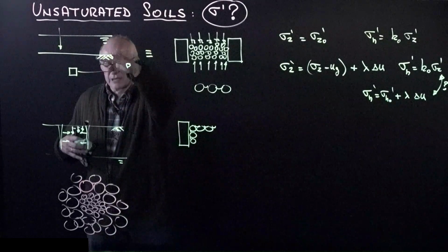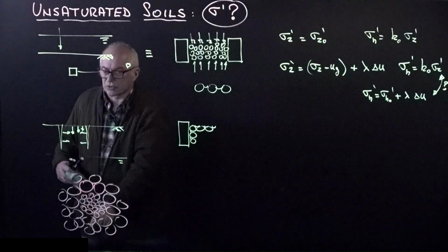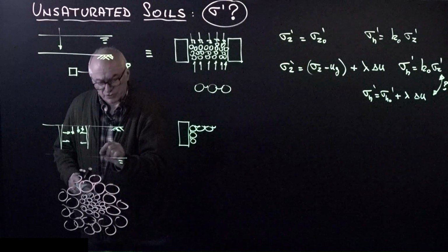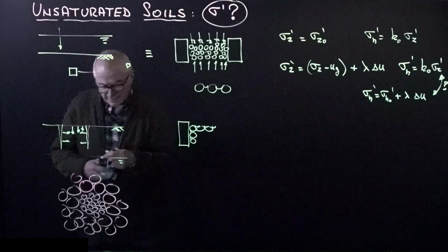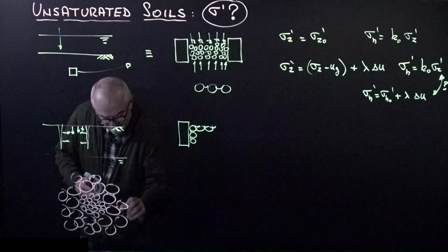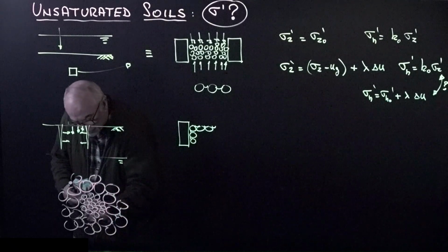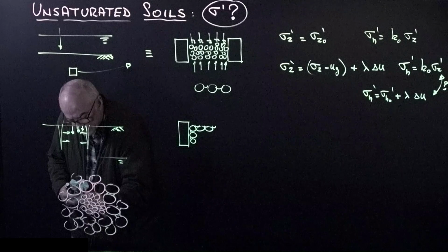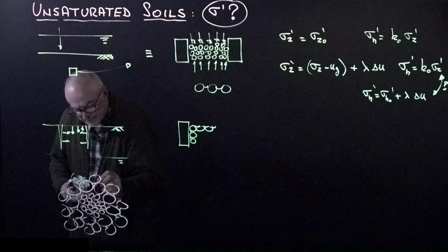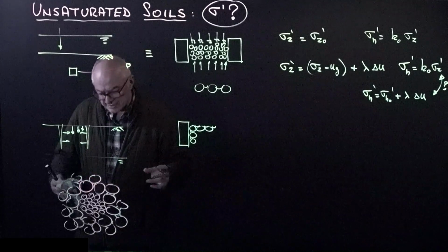The water table has gone down, it began drying, now air has invaded all the large pores, but this lens with fines has small pores. So it is very likely that there may be a little amount of water remaining at menisci between the coarse grains, having some action pulling particles together. Remember, the curvatures ought to be the same. If you draw this carefully, make sure that you draw curvatures everywhere the same, because this is being balanced by the vapor pressure and the suction.